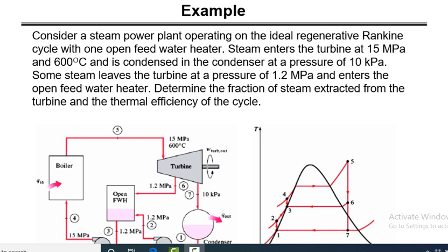That is Q equal to W equal to delta KE equal to delta PE equal to 0. Then in this system, energy in minus energy out equals delta E system equals 0. Then we can write summation of inlet equal to summation of outlet. That means in both the open water heater and the closed water heater you have to consider steady flow energy equations. First of all, we are going to take the first numerical, based on the open feed water heater.